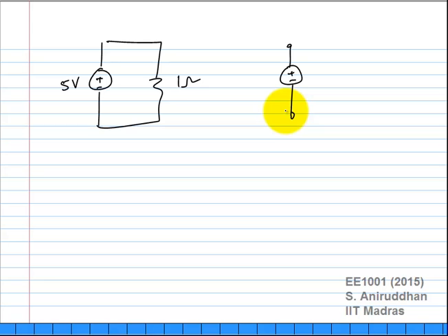This is a voltage source. So this is possible. I take a voltage source and I hold it like this, making no connections to it. Is that allowed? Of course it is. All you are saying is there is no current through the voltage source, but it still holds the same potential difference across it.